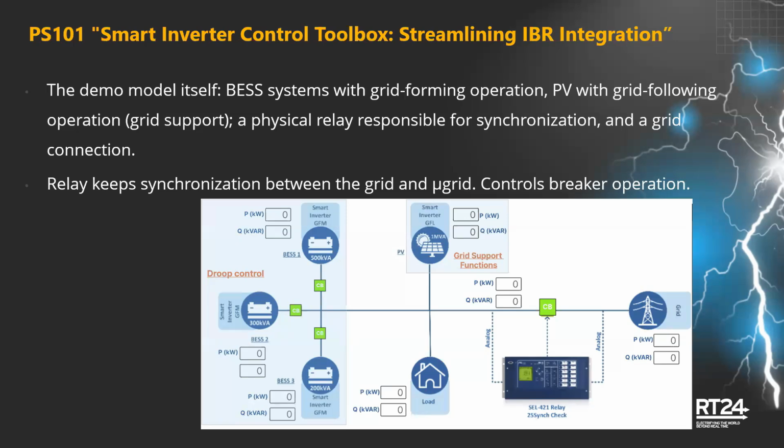And so we want to demonstrate how, using this demo and this real hardware, we can test and validate that our real hardware is properly performing the functions that it should, according to the codes that have been recently implemented. So in this demo, the key thing the relay does is ensure synchronization between the microgrid and grid.